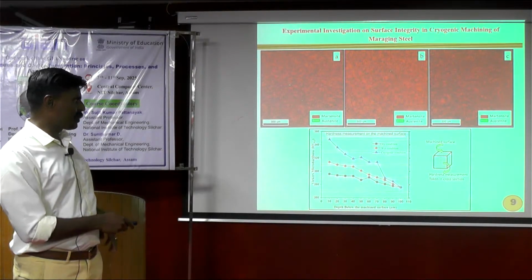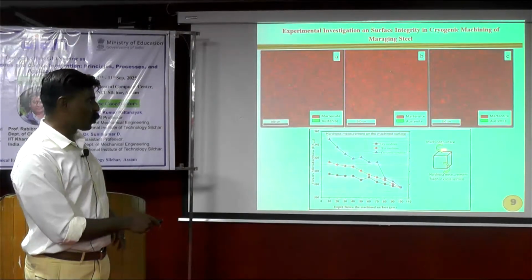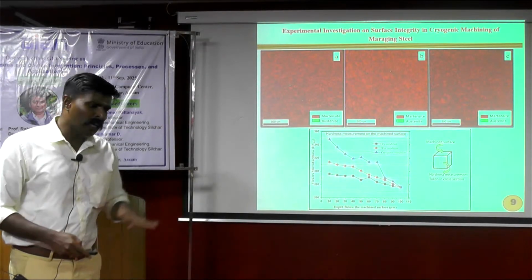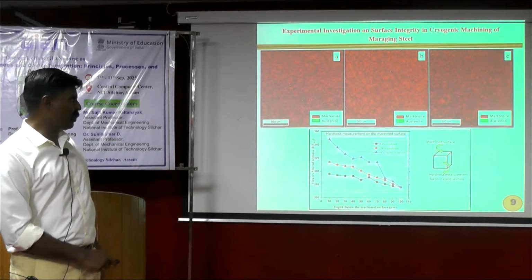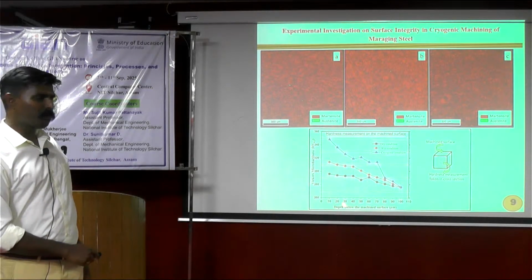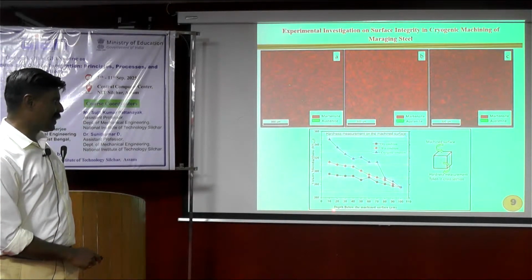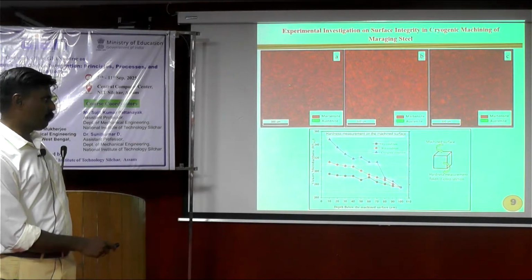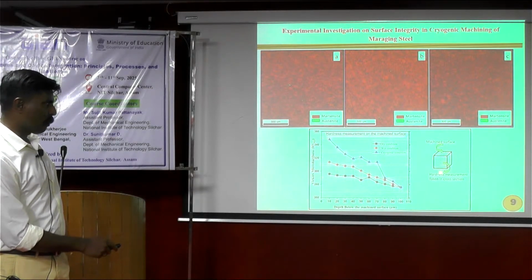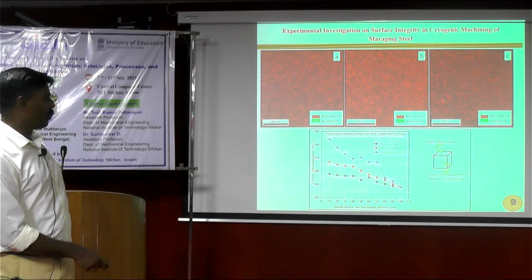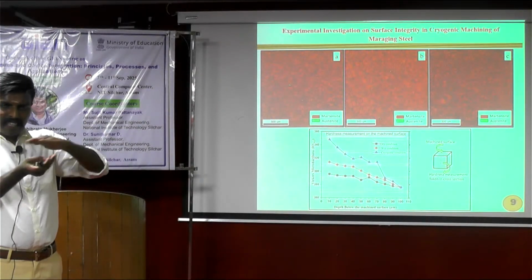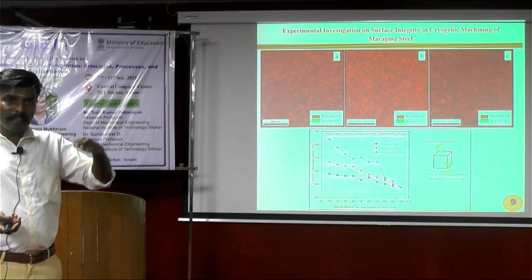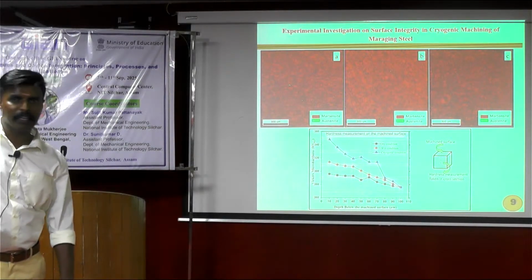So you can see this is a schematic diagram. The top side is the machined surface; there only the milling happened. But the cross section side we have taken for the analysis. You can see this is a Vickers micro hardness tester. This is the depth below the machined surface. That means this is the top area, and then slowly we are increasing the depth. So while doing machining, the adjacent area is getting more strained than the area far away. Is that correct?